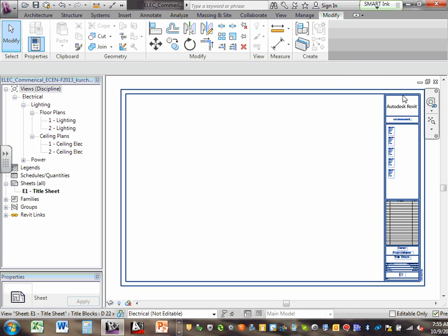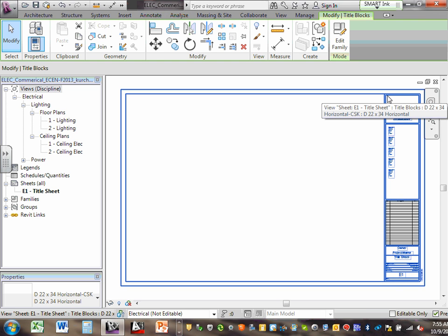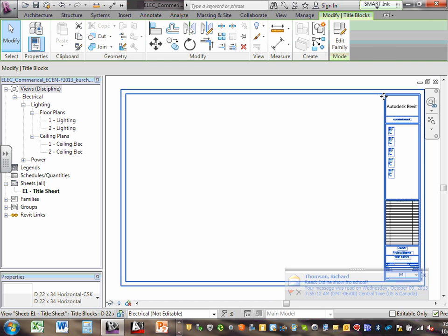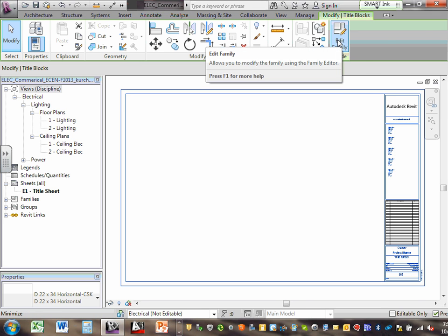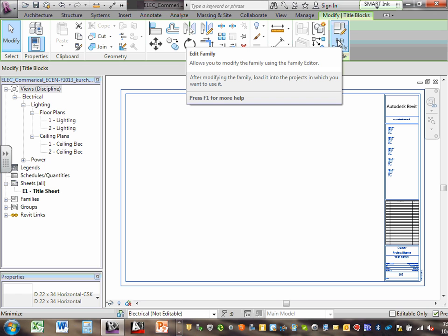Now, since this is generic, guys, I'm going to click on it. Can you guys click? Go click on it. Everybody clicked on it, it becomes blue like this. Thumbs up, Chad. And I would like you to see the concept, edit family. Now we're getting into editing the family. Why am I going to edit this family? If I'm happy with this title block, I'm done. Had this been edited before, I'm done. Just use it and keep copying it. Well, this is not my real title block, so I'm going to go edit it.